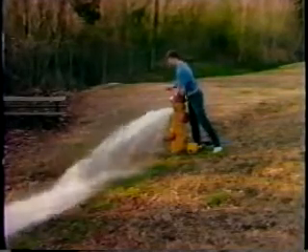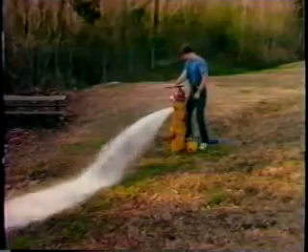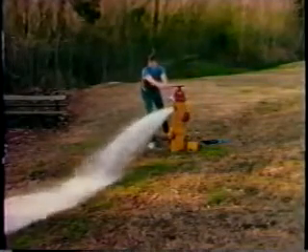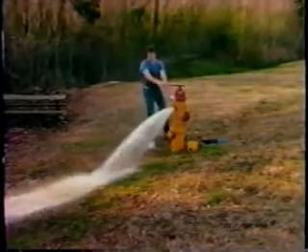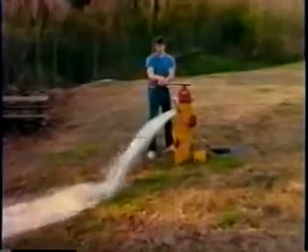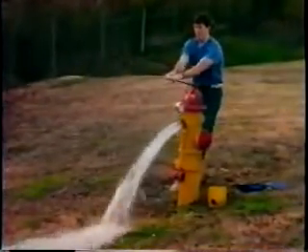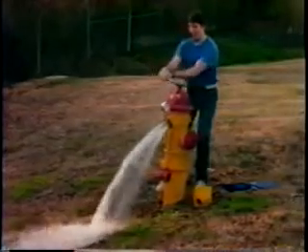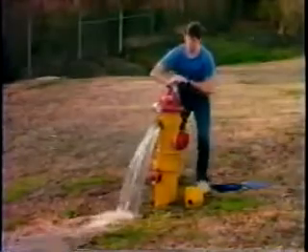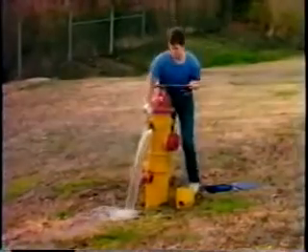The individual at the residual hydrant will be able to tell if one of the flowed hydrants is being shut too quickly, because he will notice the indicator on the gauge jump rather abruptly when the pressure surge from the closing of the hydrant reaches the residual hydrant.